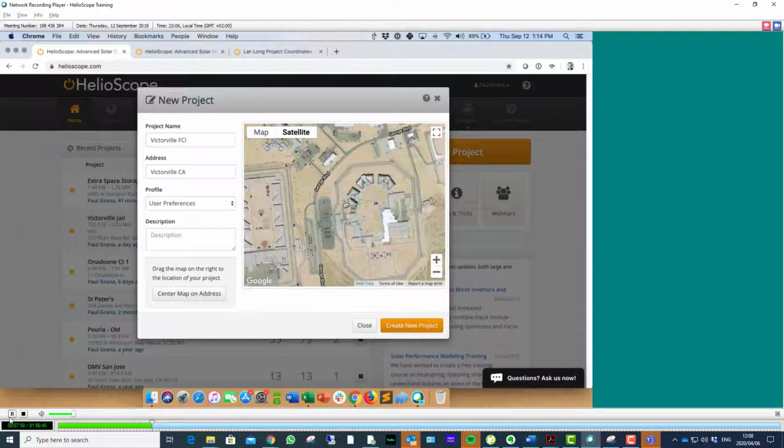That project home is pretty important because that's the 0 point for a lot of the calculations. A lot of the module distances, row-to-row shading, wire length calculations, etc., are calculated with respect to that point, which means that you want to stay within about a mile of that center. If you go outside of a mile, believe it or not, the curve of the Earth can start to lead to errors in the calculations.